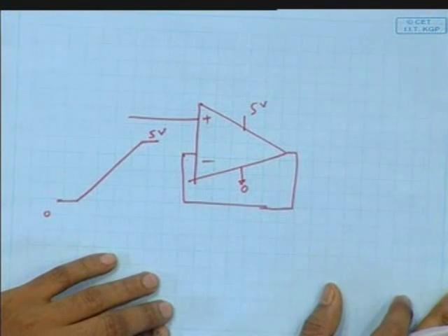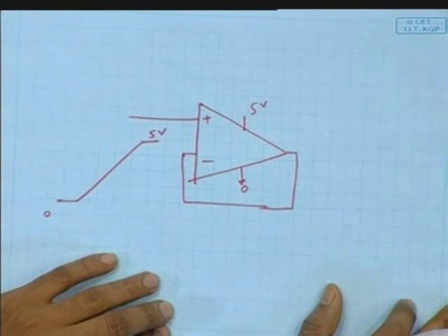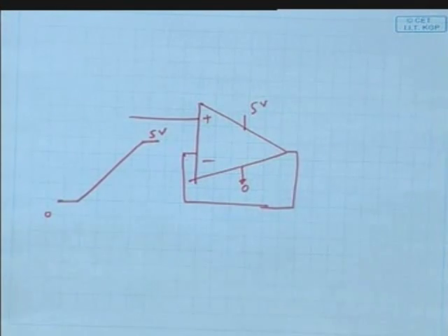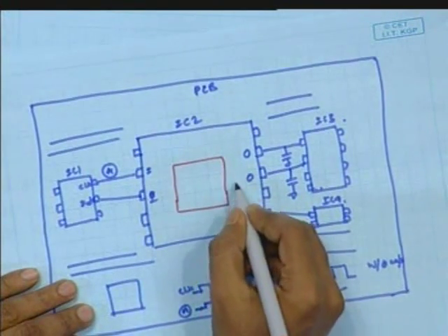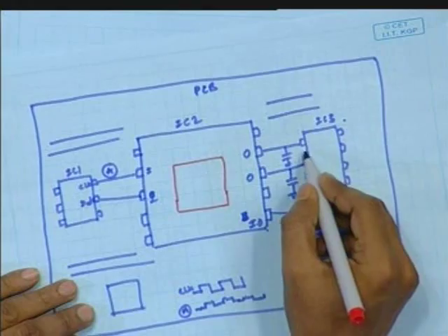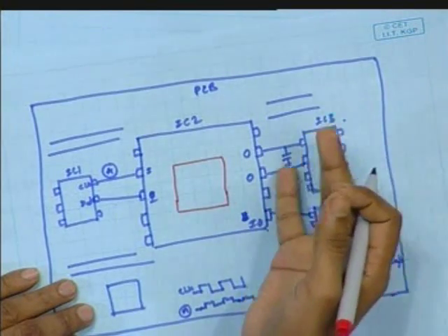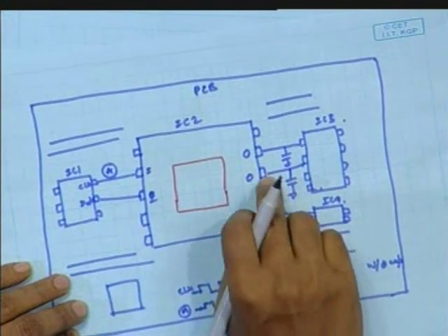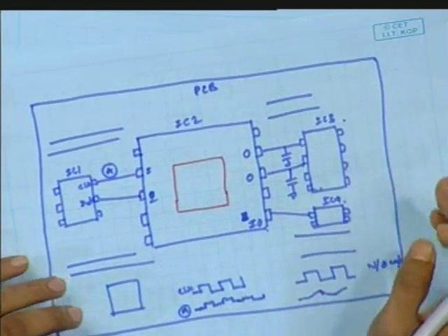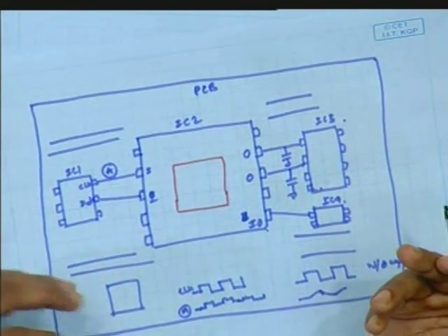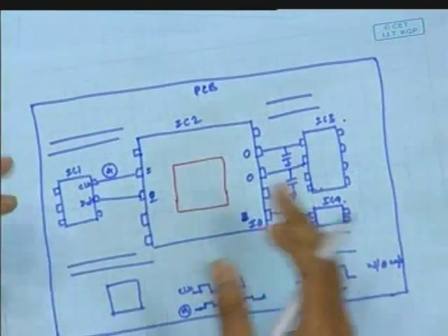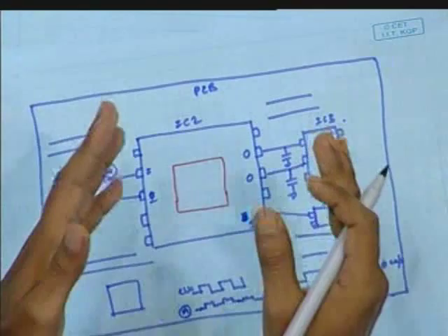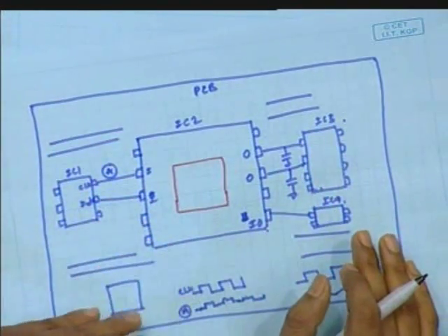Now, if you consider a high speed signal, some gigahertz signal you want to transmit, right? Consider you have a VCO. Consider this is your IC2, and we have some VCO here. And here this is IC3. We want to transmit that signal, consider some 5 gigahertz signal. We can't connect the VCO output directly to the pin, because the pin has particular capacitance, resistance and inductance that will affect the VCO. That means if you use an LC VCO, the VCO inductance and capacitance will change, so the operating frequency will change, and we need some isolation buffer.